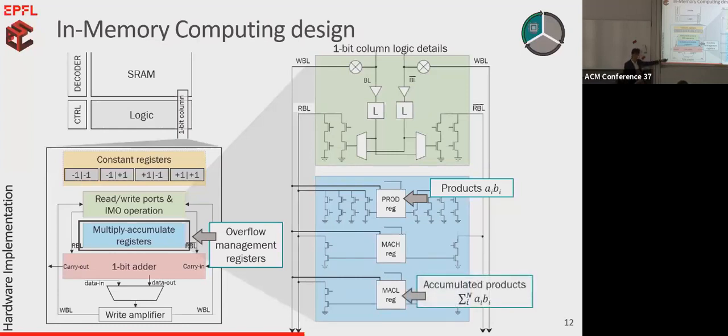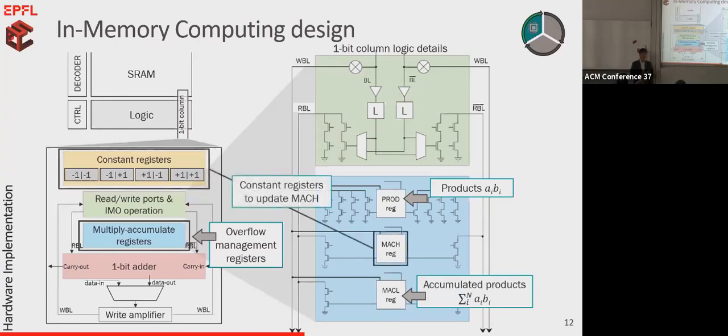Notice that now the MAC register is split into MAC-L and MAC-H. We actually perform accumulations in MAC-L, but every time there is an overflow, we increase by 1 or -1, depending on positive or negative overflows, the MAC-H register. So that's an overflow register, basically.